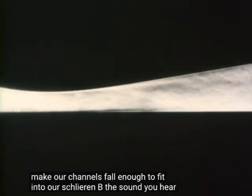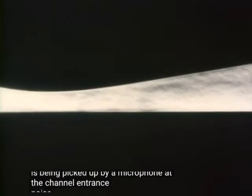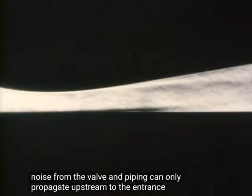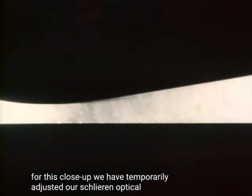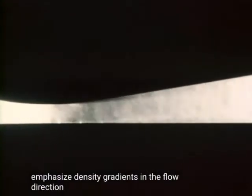The sound you hear is being picked up by a microphone at the channel entrance. Noise from the valve and piping can only propagate upstream to the entrance if the entire flow is subsonic. For this close-up, we have temporarily adjusted our Schlieren optical system to emphasize density gradients in the flow direction.